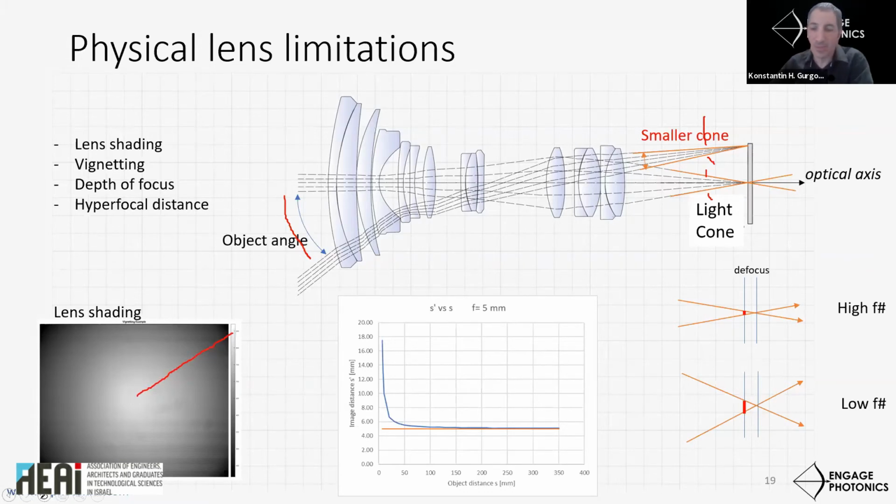This is the general expression for lens shading. However, that's just a first-order approximation, and the actual lens shading depends on additional parameters inside the lens and its matching to the image sensor. So in some badly designed lenses, the light beam gets truncated on internal lens edges, which causes another contribution to lens shading, and that is called vignetting.